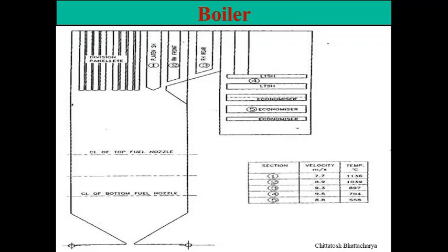They are placed at the second pass. These are part of primary superheaters. Then from there it is going to the platen superheaters. From there, final superheaters. Final superheaters are placed in the joining of the radiant and convective zones, and subsequently it is sent back to the HP turbine, as superheated steam, final superheated steam.